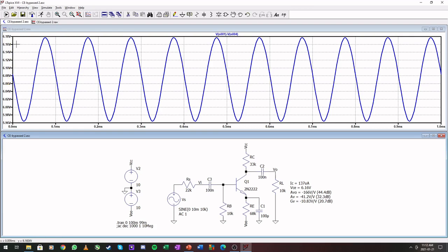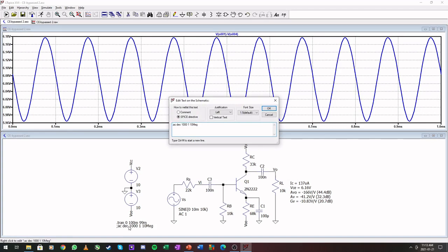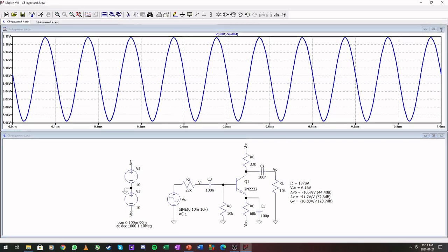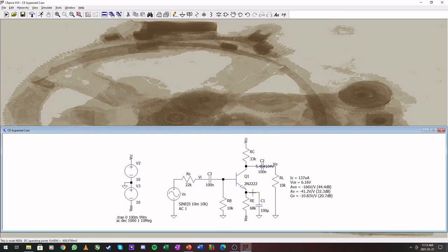This is a little bit off. We should be up there, but who's looking at the 80 millivolts that we are missing? That is not much. So yeah, our DC point. Another way to do the DC is by closing this, and then when you click on these nodes, the voltages will actually show on there. If you didn't know this, that is a nifty little trick.